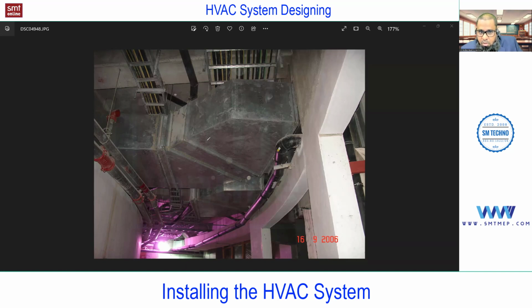So you see, first of all, in order to decide this, experience is required, and that's the reason in actual practice, this decision is taken care of by the architect or a senior mechanical or electrical engineer, because without experience, you cannot decide this. And above the false ceiling, you'll find limited clearance, and in that clearance, we need to set all this. So there is no question of reducing this cable tray height, because this is a standard. We cannot work on this. And even these pipes, the firefighting pipes or drain water pipes, we don't have much scope to reduce, because this is based on the design.